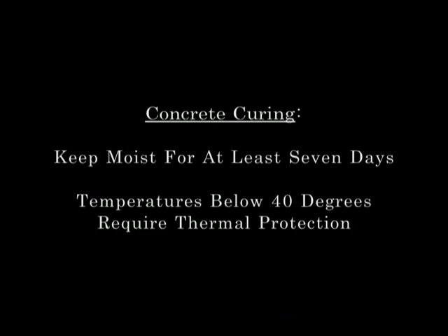After your concrete is finished, you need to let it cure properly. In order to do that, you want to keep it wet for at least the first 7 days. A proper curing takes about 21 days, and the first 7 are the most crucial. In that time, you achieve most of your strength, and if you do not cure it properly in this time, you'll get cracking in the surface of the slab and other structural defects.